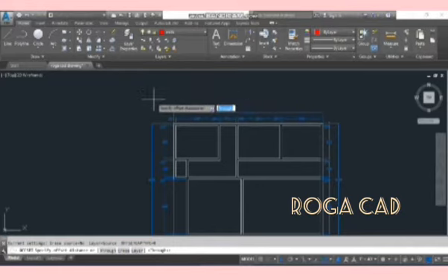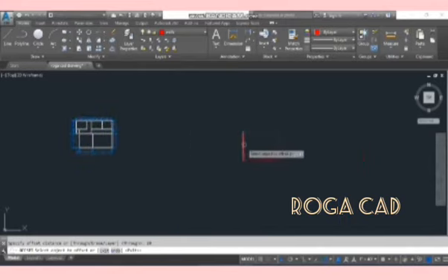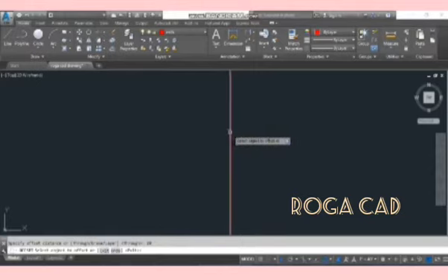drawing area, and then you press 20, which means that this is the thickness of our wall. As you know, most of the time a wall has a thickness equal to 20 centimeters. So you press the wall that you are going to offset, and then the 20 comes, and then you press enter.